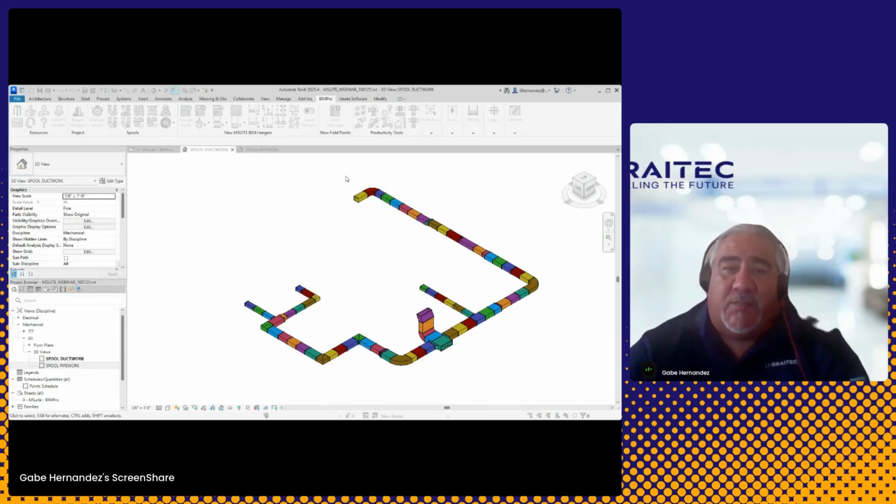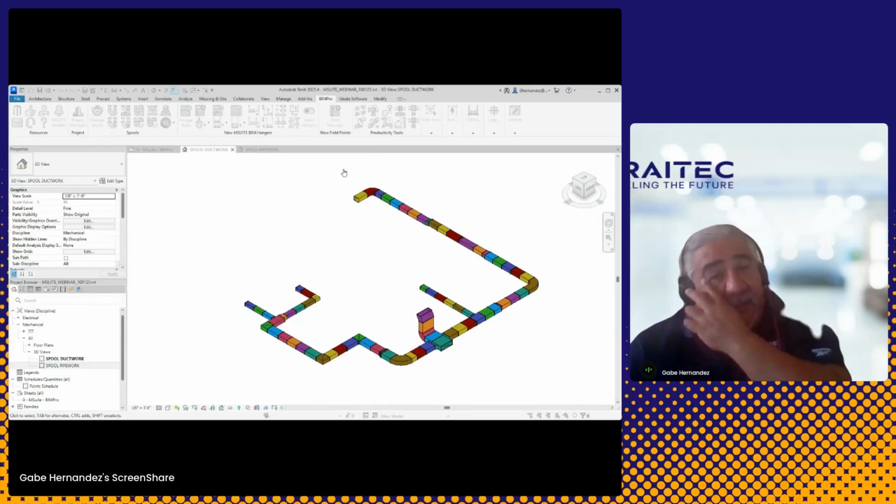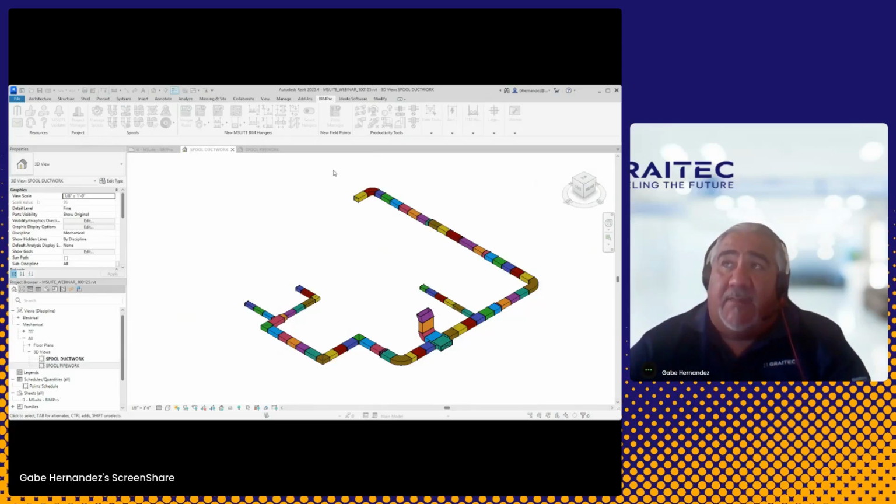The uploading is where you would upload these spools to the shop component, right? So I can upload these to the MSUITE server and take those into a job under the Fab Pro side. So it kind of goes from BIM Pro to Fab Pro in that sequence. And then I have my exporter for MAJ and my Fab data. Once it goes into the Fab component, I can pull spool data back directly into these spools as well, like completion, percentage of completion, workflows, due dates, statuses, etc. Right? So it interacts with the shop as well.